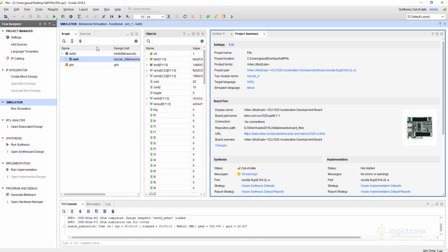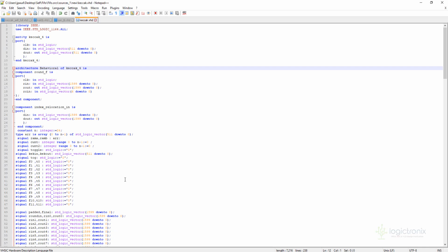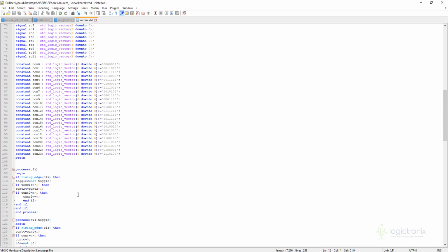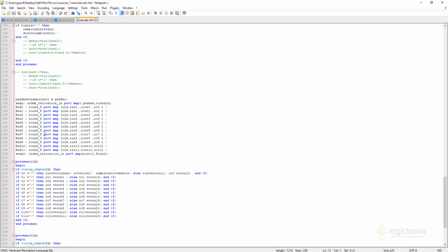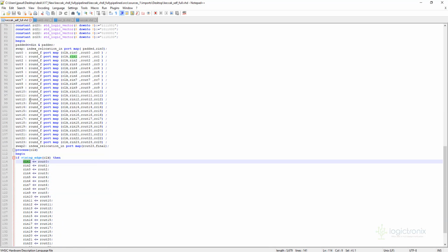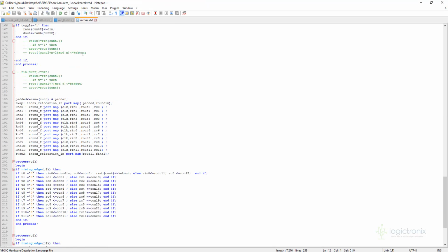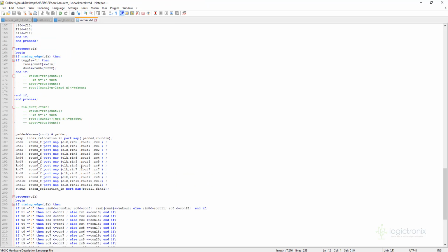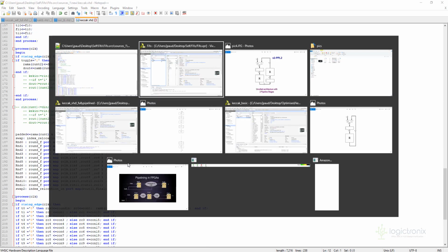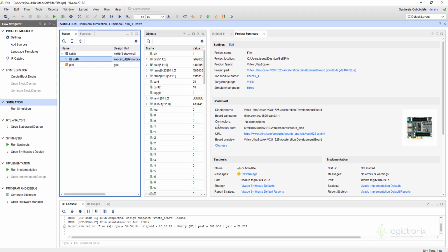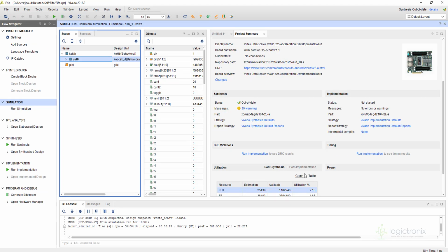So here is our architecture with 12 pipeline stages. This is the same Keccak, like fully unrolled, but it has only 12 rounds. So we will be able to give input every 2 clock cycles instead of 1, and its area will also be half.